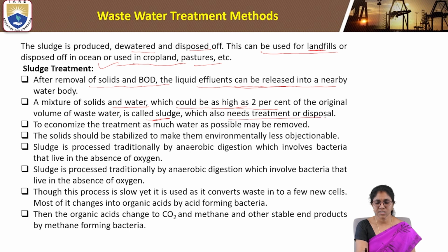This sludge also needs treatment and disposal. It is a mixture of solids and water, as high as 2% of the original volume of wastewater. To economize the treatment, as much water as possible may be removed. The solids should be stabilized to make them environmentally less objectionable.